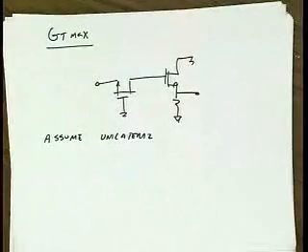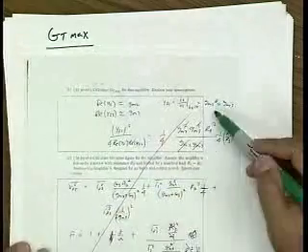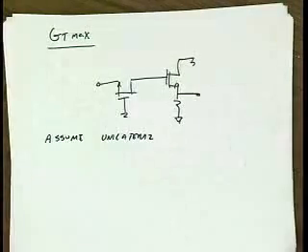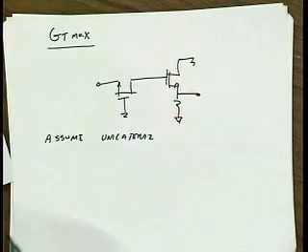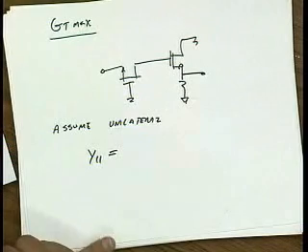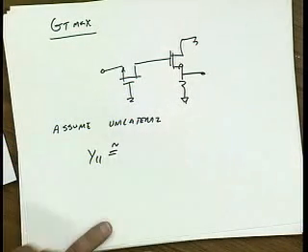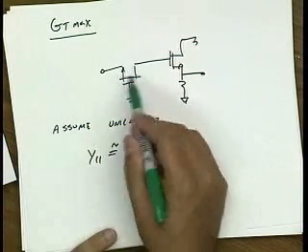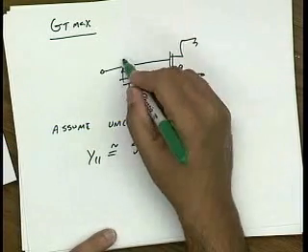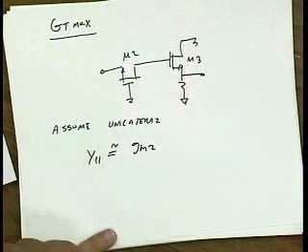And there's a hint that it should be very simple because look how much space you're given. Right? So if you have to calculate y parameters for y12, forget it. You're going down the wrong path. Okay, so what's y11 approximately? Well, y11 at moderate frequencies is just basically GM2. Right? This is M2, this is M3. Okay?